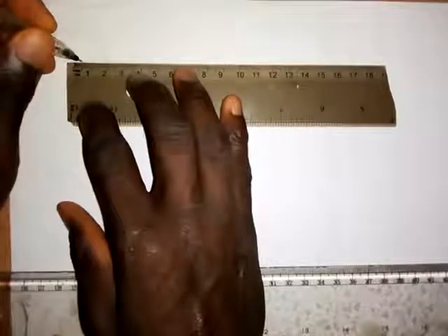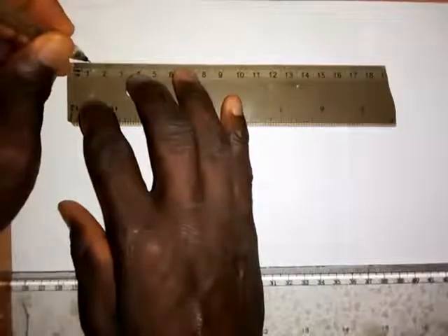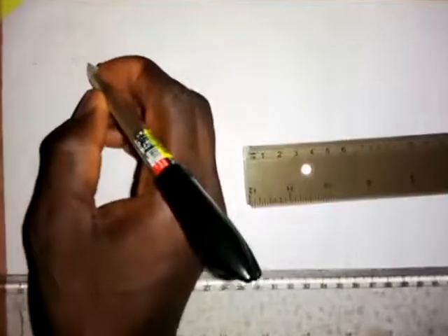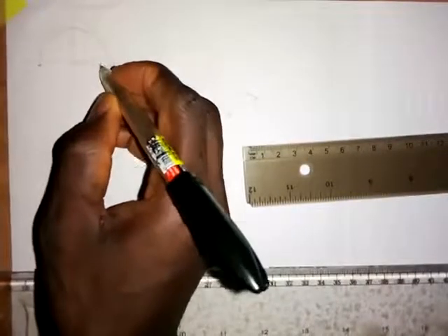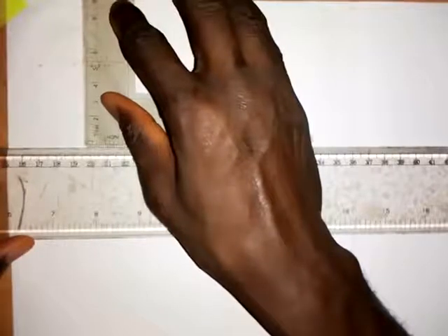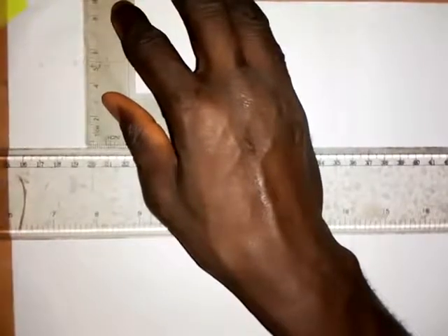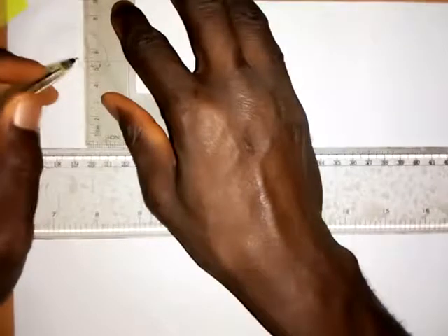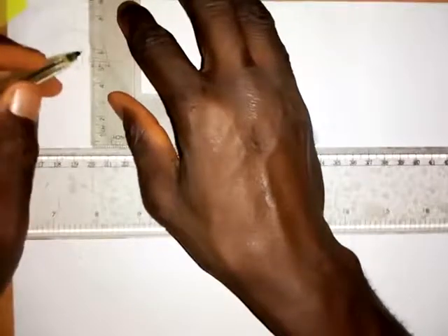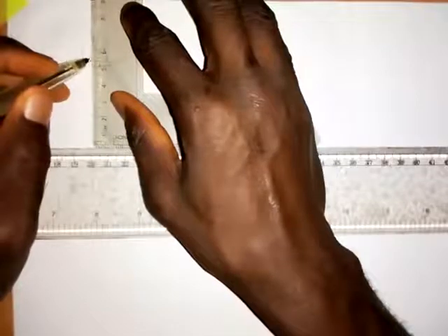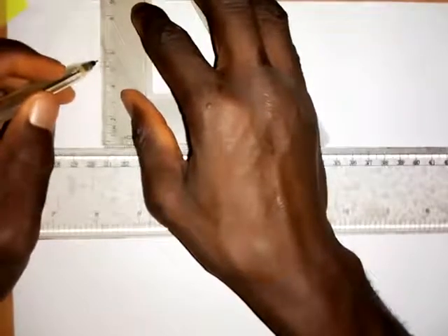So that is 5 mm each. Alright, so this is 1. So this is 2. And this is 3. So here we have 4. So the next thing I'm going to do is that I will draw a vertical line at each point meeting the curve. So this goes like this, and I have this. So this is another method that you can use to construct an isometric circle.